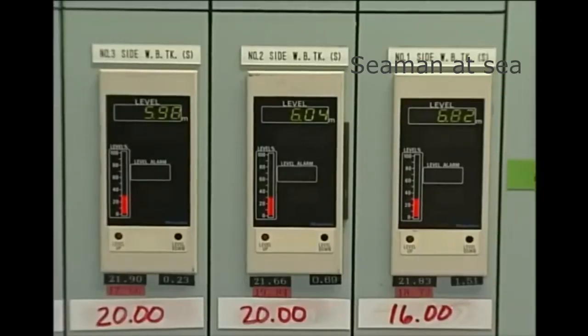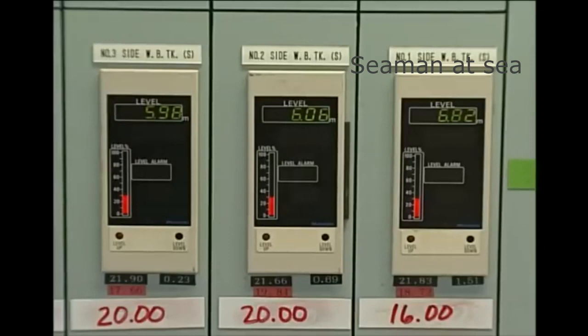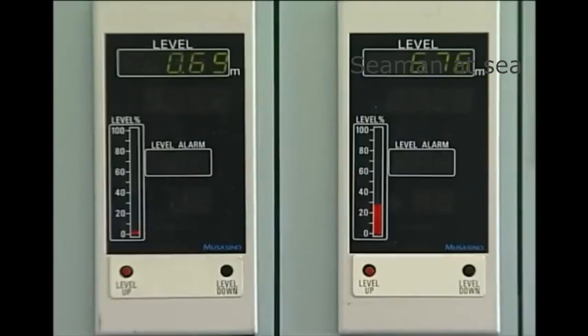Watch water level, since cavitation occurs as the level drops, which causes the water head pressure from the pump suction valves to decline. As the water level drops further to approach the tank bottom, now exercise precautions against air drawing. Watch the gauge carefully and readily respond to the risk of air drawing.